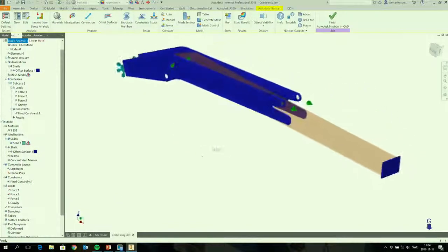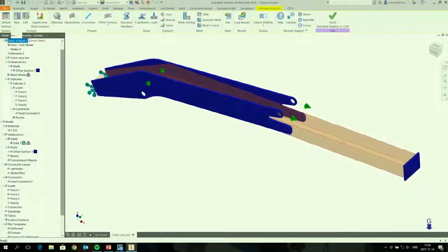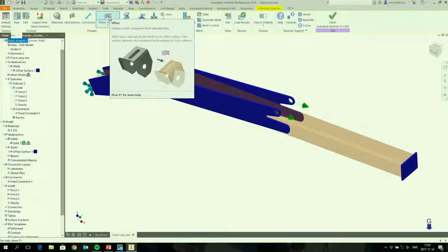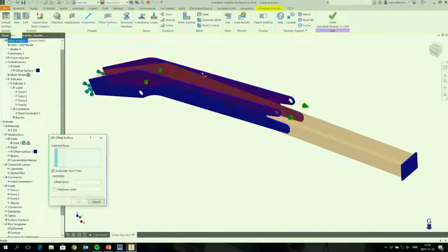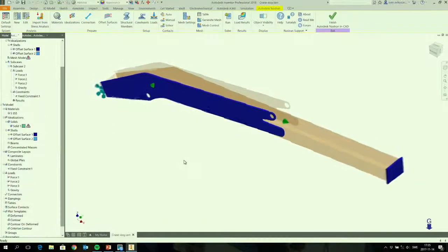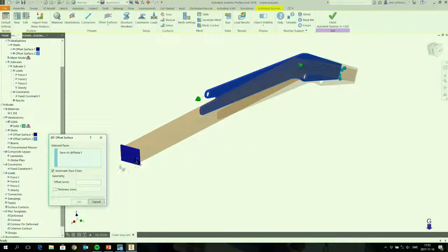Okay, so now you see I have got the transparent surfaces, which do have mid-plane defined on them. They don't automatically have any elements yet, but it's defined to be mid-plane. I continue with the other ones. They are not really thin, but I want to run thin plate on every one. So I take all the 4 surfaces.